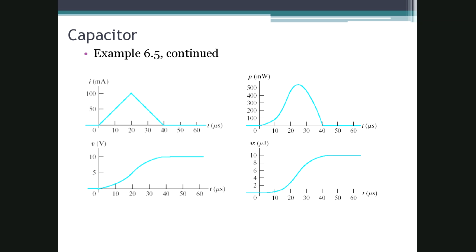Okay. So remember that initially we have two plates, and one side is negative, the other side is positive. What's happening initially in the capacitor in physics is that you are building up this electric field. It initially looks like a short to voltage, right? So we have this point right here where you initially have the voltage at 0. But as this field starts building up across the capacitor, we're allowing some current to flow, and we're developing a voltage drop across this capacitor.